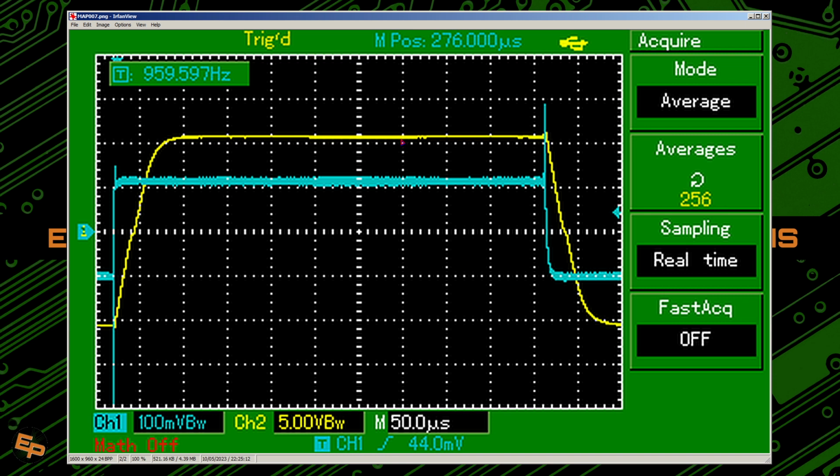The entire circuit is powered by plus minus 15 volts. I forgot to mention that earlier. So if we multiply 100 millivolts by 100, we get 10 volts. So the op-amp will output plus minus 10 volts, which is within the range of acceptable voltages for the output of LM324 when we're having a plus minus 15 volts differential power supply.